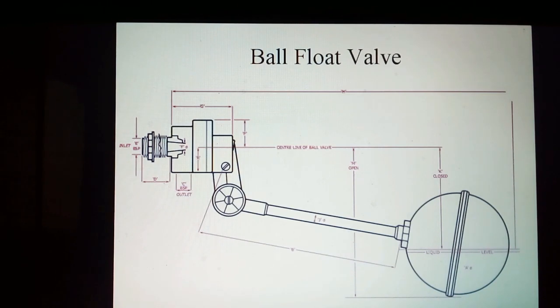It consists of a valve connected to a hollow sealed float by means of a rigid bar, which is mounted on the top of the tank. The valve is connected to the incoming supply. It works on principle of maintaining the level of free water surface. A float valve allows water to flow until a predetermined level is reached. Once water reaches predetermined level, float will rise with water due to buoyancy and stop the flow of water. As water level drops, the valve will open to refill the tank.